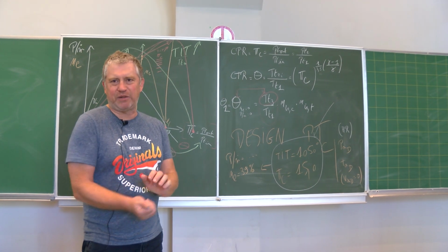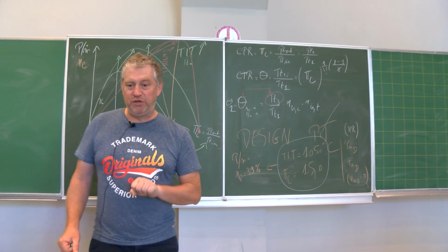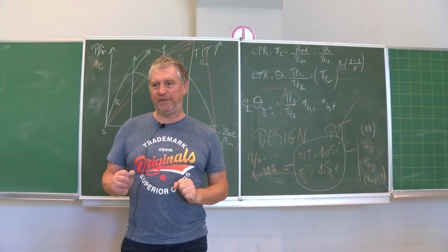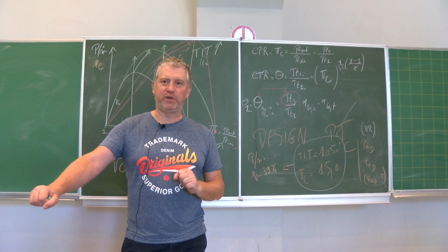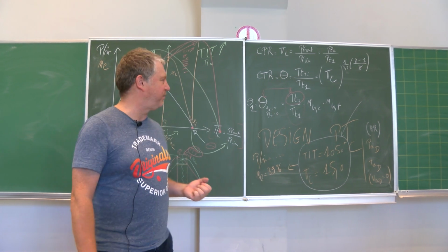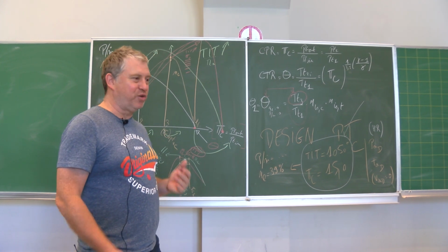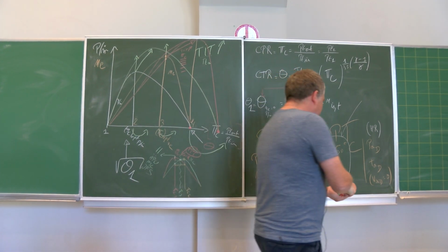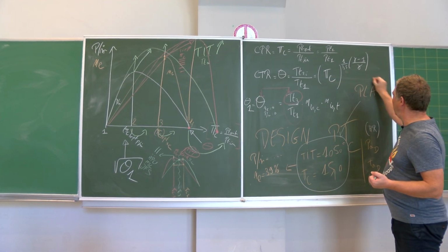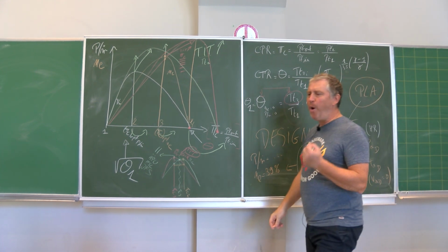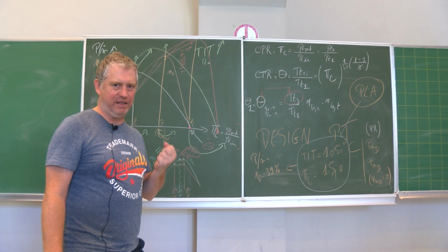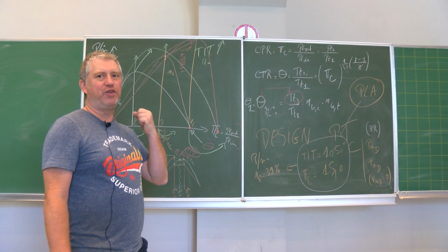That is, in an aircraft engine, the throttle that you move in front of you in an electricity production unit, or in an aircraft that you push in a civil transport aircraft with your right hand, and in a military aircraft very often with your left hand. So this is a parameter that I will summarize very often as the PLA, the power lever angle, the position of the gas handle, of the gas pedal, of the throttle.